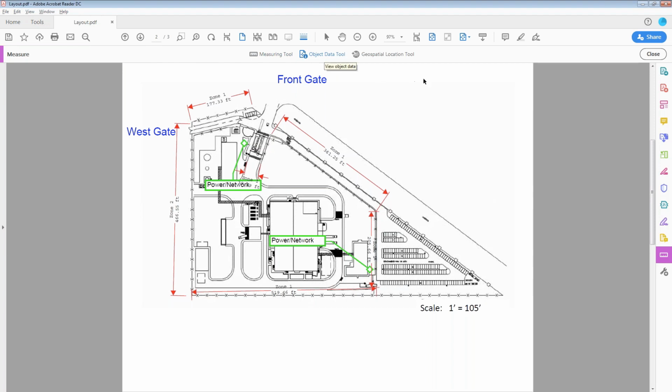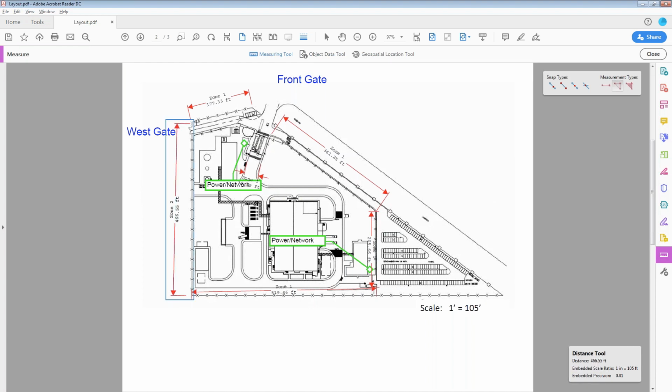Now I might want to look at the entire perimeter or split up the perimeter in a certain way, so I'm going to do a compound measurement in this case. I'm probably going to set up one system, let's say from here to this corner, which is 980 feet. You can see it at the bottom there on my cursor. If I click it, the one thing you lose when you do a compound measurement is the number. That 900 and some feet disappears.